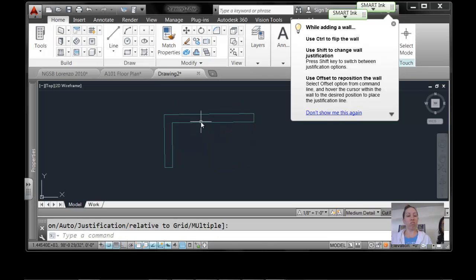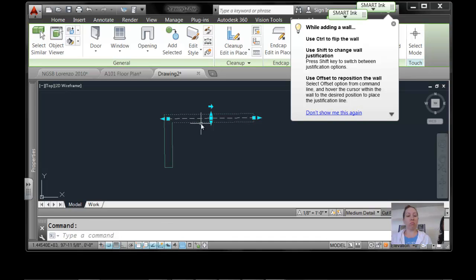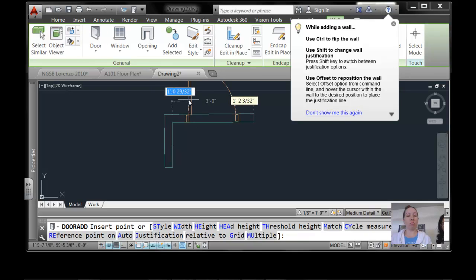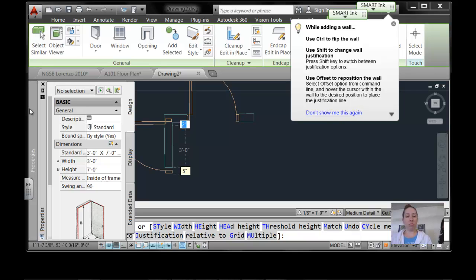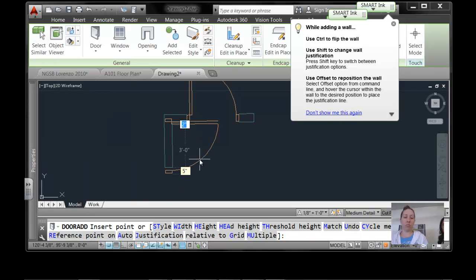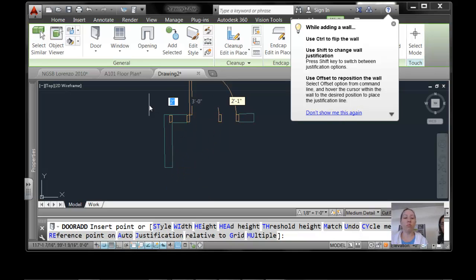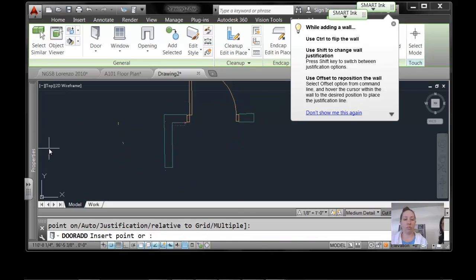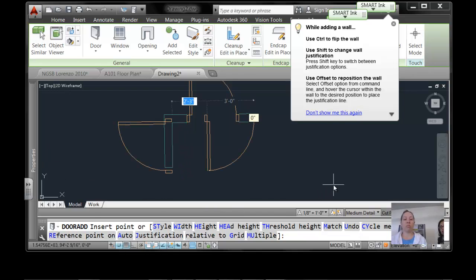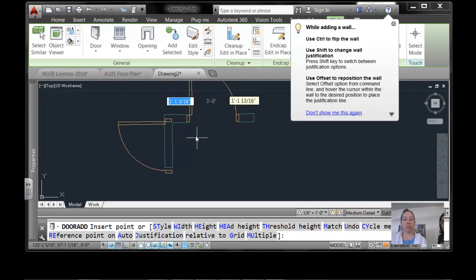Okay, so why it's not applying? What's happening? Sometimes if the wall is too small, okay, there it is. So click on the outside, but if there's not enough room, see if your wall is smaller than that. But I think you gotta move the cursor outside far away, and then click again, left button. There it is. The second one is kind of going crazy because you don't have enough wall. But that's basically how you enter a door or a window onto the wall, and you gotta make sure you have enough. And then what happened, the mouse needs to be far away from the wall. Otherwise it's not smart enough.